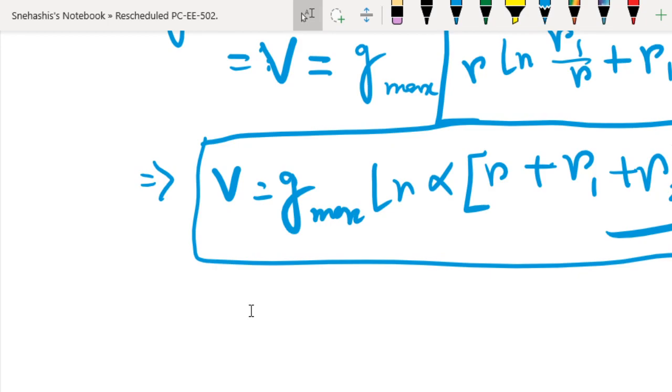Now there can be other arrangements of intersheaths as well as insulating material thickness between successive intersheaths. Okay, the grading theory is more. Now listen to the conclusion of what we have done so far carefully. The grading theory is mainly a point of interest from the theoretical point of view only, rather than practical. Why? Because capacitance grading is difficult.